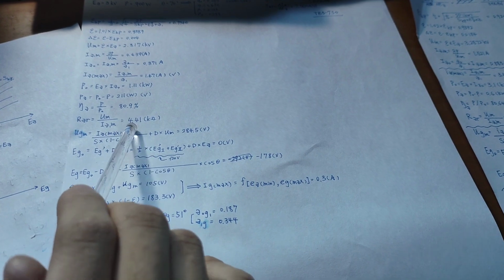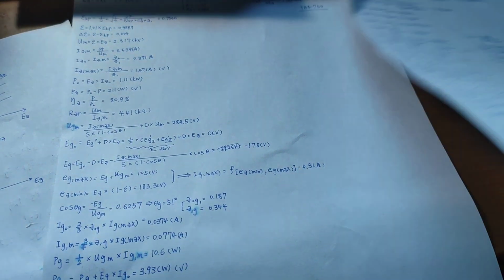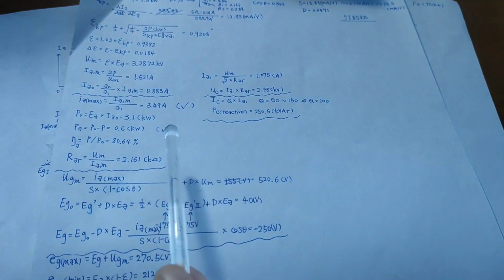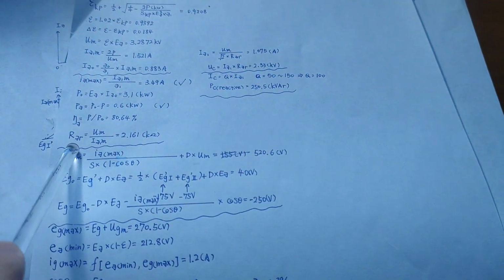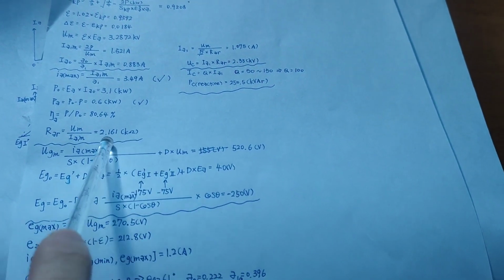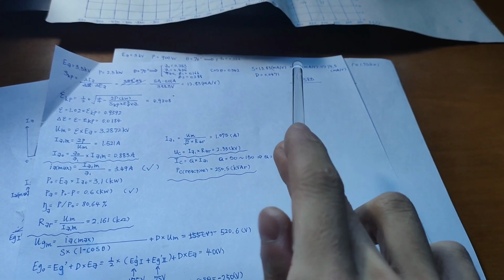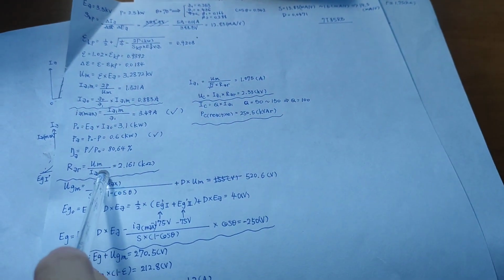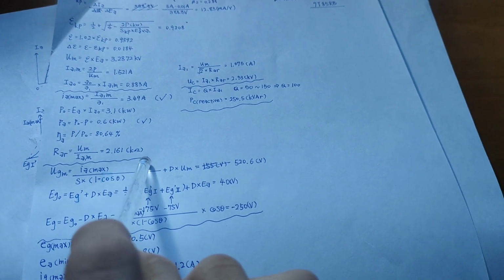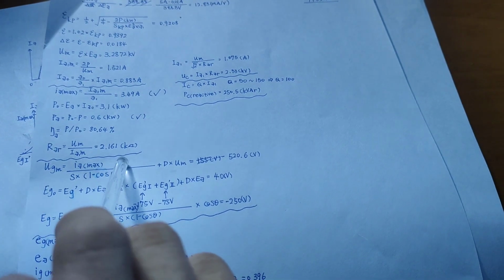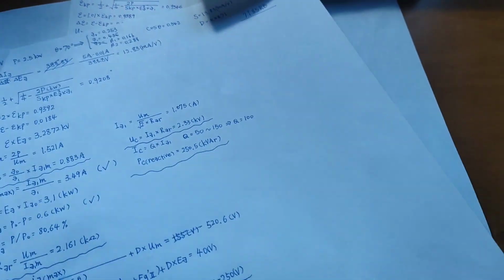In this tube it is 4.4 kilo ohms, and you can see in this larger tube the resonant anode impedance is just around half of that value. The larger your tube is, I mean the higher the power is, usually this value will be less, but it will usually lie around 1 to several kilo ohms. Keep that in mind because you can use that to check your calculation.